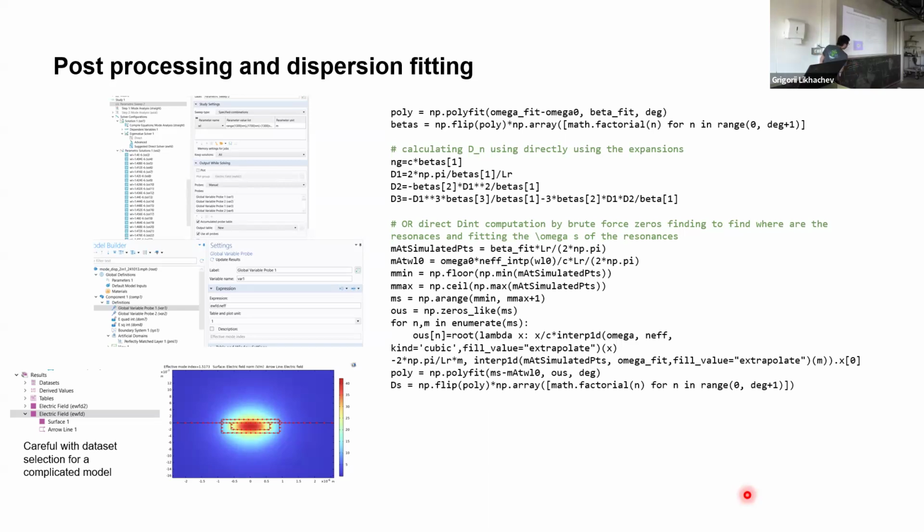For example, one problem that I'm working on these days, I have a silicon nitride waveguide, for example, 5 micron wide and 200 nanometer thick. What I consider is, if I vary the waveguide thickness by 5 nanometers, how much the effective index will change.